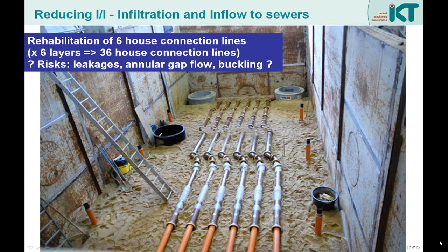In a one-to-one scale test, we check the performance of house connection liners against a rising groundwater level. On this picture, you can see 6 house connection lines in our large testing facility. They are 15 meters long and affected by various simulated damages like holes and cracks.